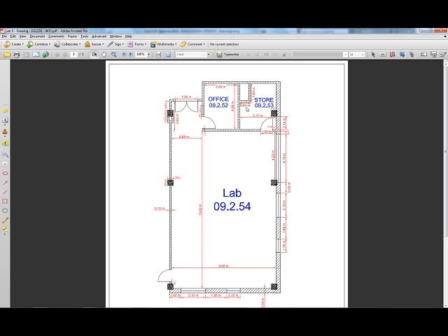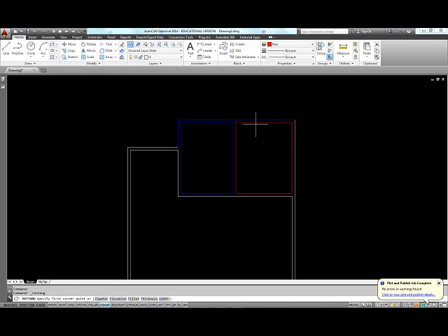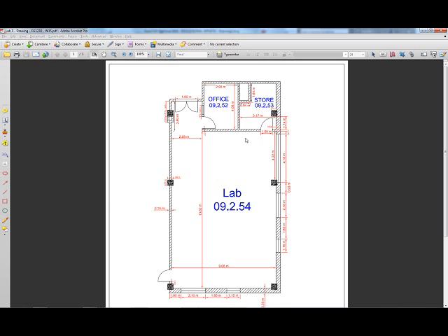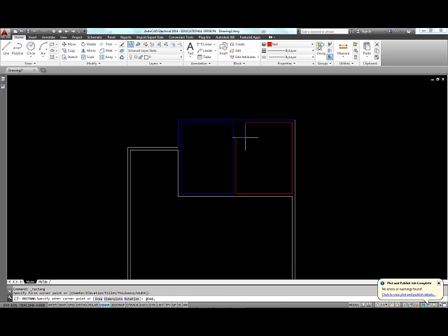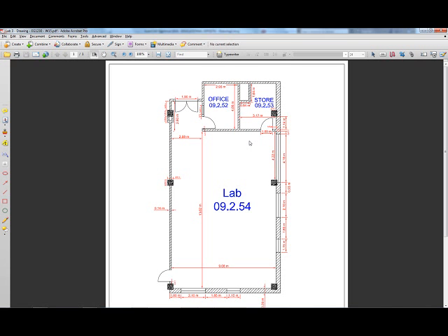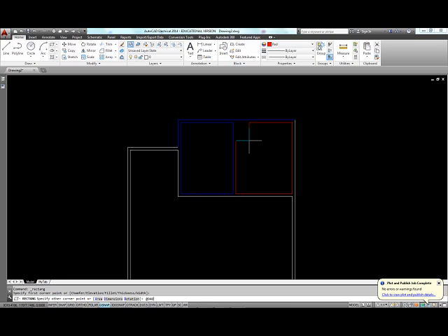Let's do this one. This has dimensions of 940 millimeters by 1640 millimeters. So rectangle at this corner at 940, comma minus 1140, enter. Sorry, it's not 1140, it's 1640. So Control Z to undo, and then let's do it again from here at 940, comma 1640.